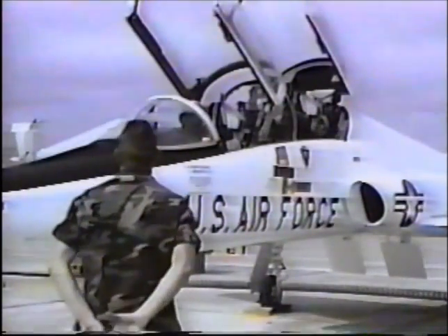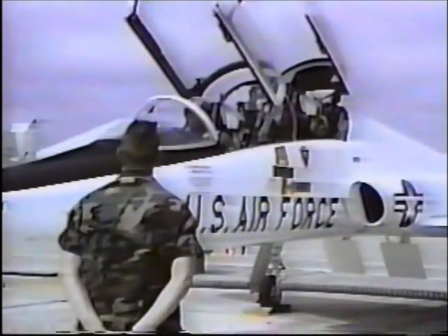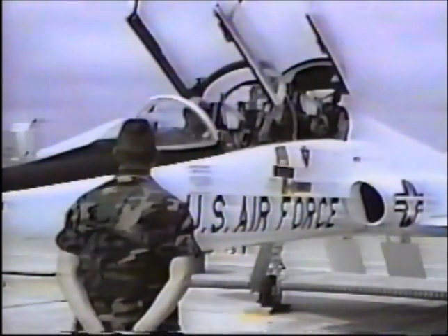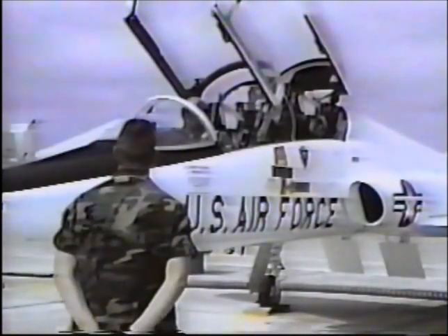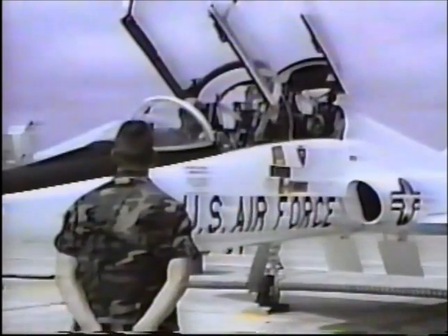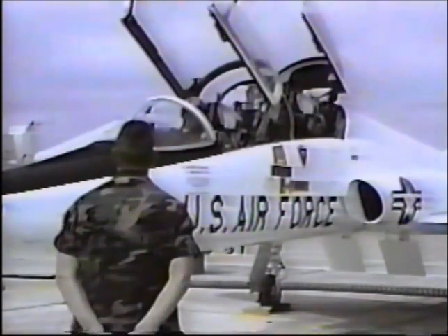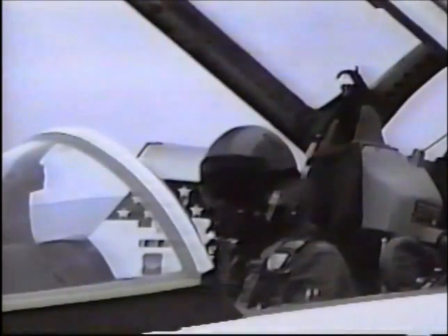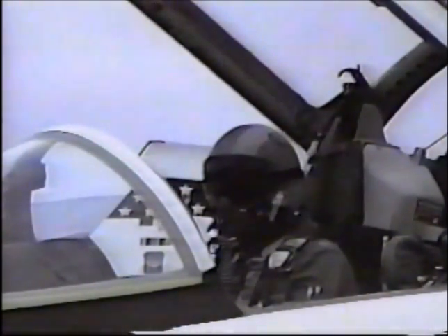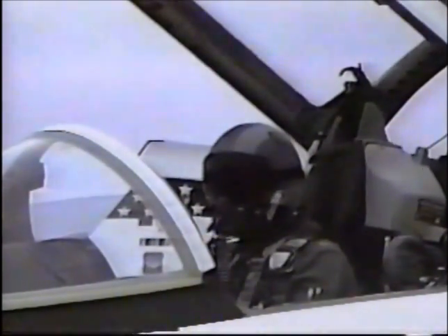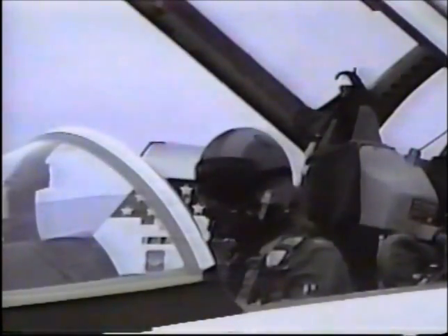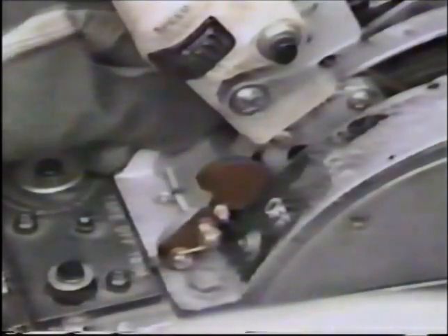There's 14% RPM. Ready, half. Throttle time. Fuel flow is 300. Oil pressure indicating. EGT is rising. 700 feet. My engine instruments look good. Hydraulics look good. Caution lights are out. My engines check good. Hydraulics look good. Caution lights are out. Throttle gate is engaged.